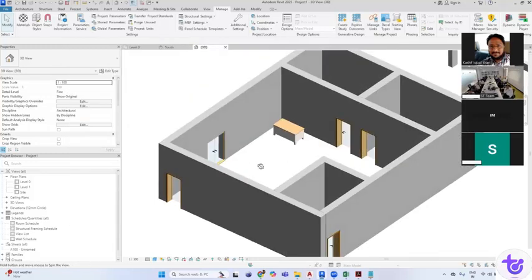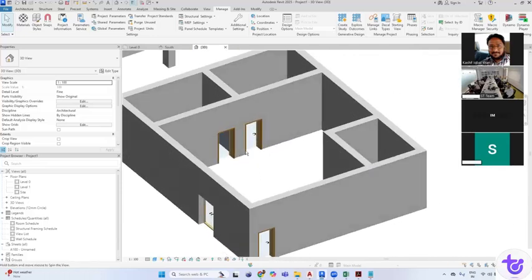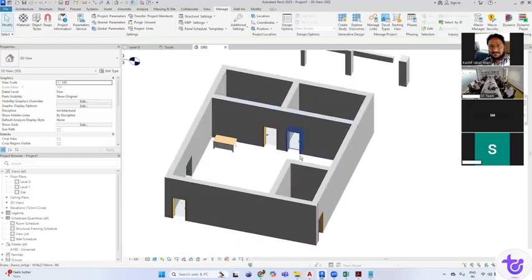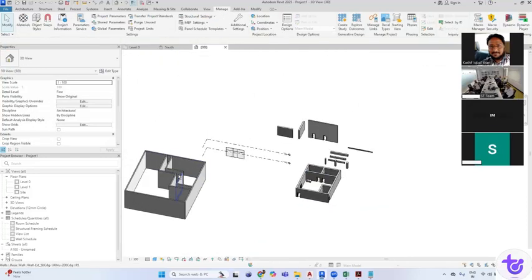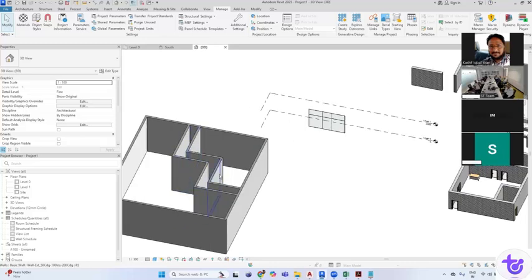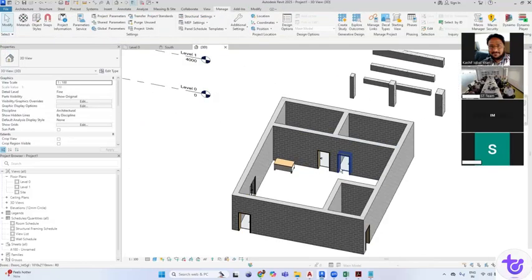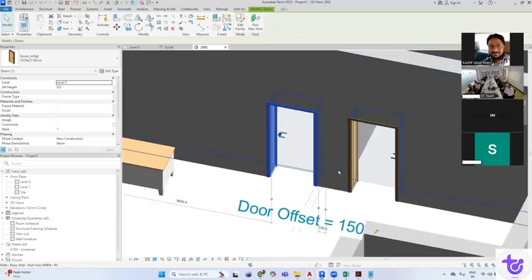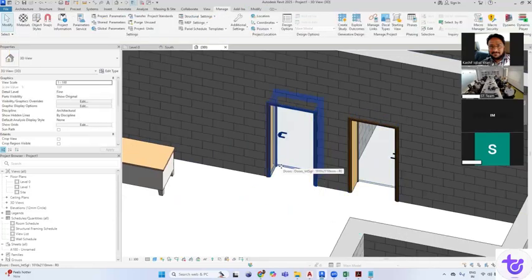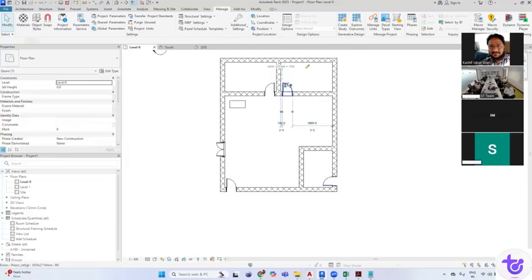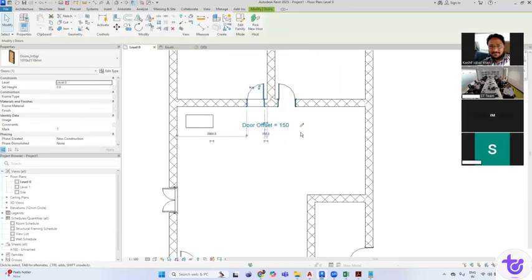So, I mean, there are a number of ways we can apply in our daily requirement, not only specifically to the door material, you can change the furniture material as well, anything. More specifically, I found it more useful for constraining the dimensions, particularly for door offset from the wall. This is always a pain. Sometimes it displaced. So we can just add a dimension and set it to the global parameter. And then you can delete the dimension also, because if it looks ugly there in the floor plan, few dimensions are floating, you can delete, but still it is there. The parameter has been set there.